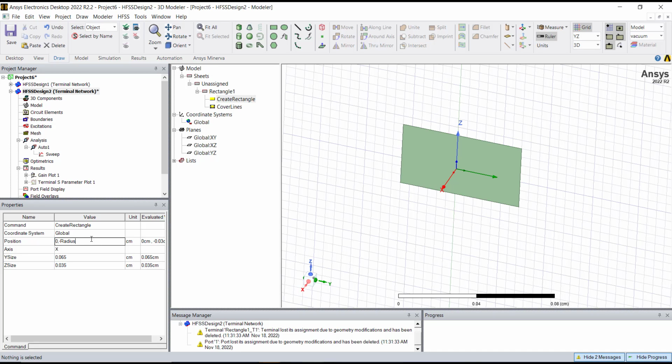I believe this is probably case sensitive. So I've got the X position with a comma, and now I've got the Y position not as a number, but as this negative radius. Before I hit enter, I'm going to put another comma, and now I'm going to choose negative Height, and I'm using caps. So now watch what happens when I hit enter.